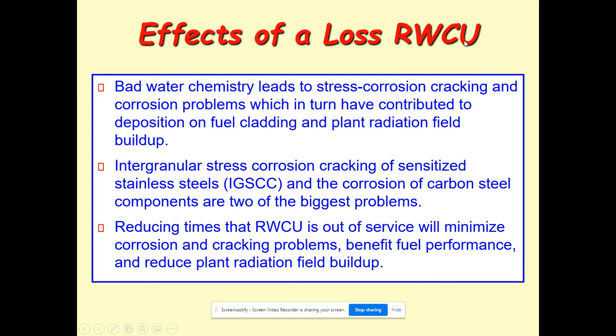So if you lose reactor water cleanup, it is not an emergency. It's a problem, but it is not an emergency, right? You're not going to melt down the reactor because reactor water cleanup went away. But you're going to start building up corrosion and crud on your fuel. So that is going to make the heat transfer worse, which could eventually, after a month or two, if you kept running it with no water chemistry, cause fuel to melt because there's not as much heat removal. But in the short term, it's not going to be a huge problem.